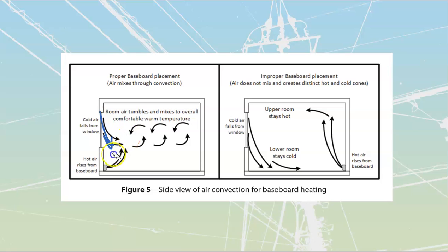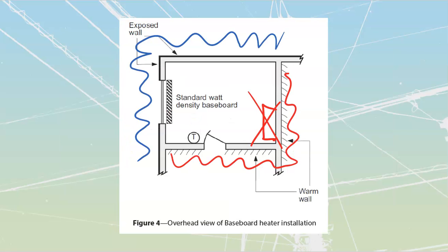So when you are doing your placement, place them in the area that is going to be the coolest, because the coolest area is going to cause us to mix and push that air across the room.